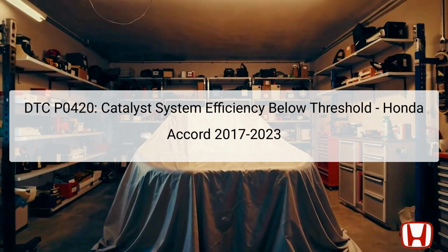In the Honda Accord from 2017 to 2023, the catalytic converter is located underneath the vehicle, integrated into the exhaust system, positioned downstream of the engine's exhaust manifold. When the PCM identifies an issue with the catalyst's efficiency, it triggers this trouble code. It's crucial to address this code promptly, as it can lead to increased emissions and potential engine damage if not resolved, emphasizing the importance of maintaining the vehicle's exhaust system. Understanding the implications of this error is vital for proper diagnosis and repair.